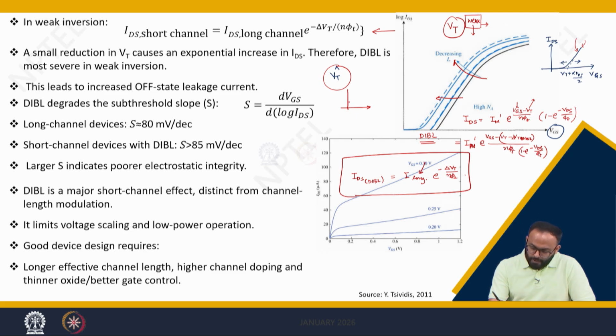However, the slope of the graph also reduces, because the change in the threshold voltage increases the leakage. Earlier you were expecting this graph, but now in this DIBL condition you are expecting a graph like this. So, ultimately the subthreshold slope gets deteriorated when the DIBL effect comes into the picture.